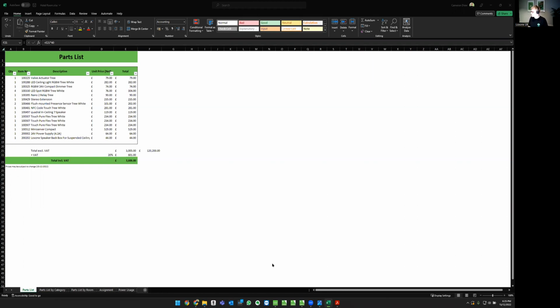so that room 49 can say, oh, I've got a call for heat. I need to start heating up. My valve actuator is going to, for argument's sake, let's say 50%. It will send that information over Tree back to that central Miniserver, and that Miniserver will start running the likes of the pumps and the zone valves.